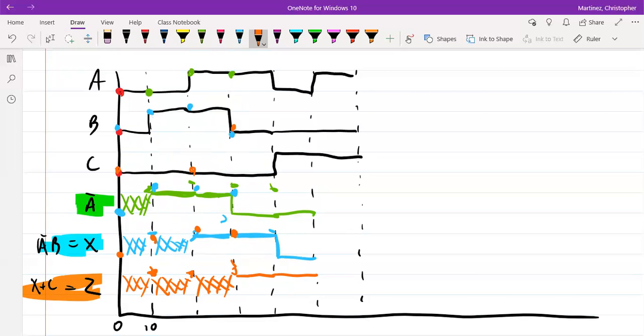All right, so that takes care of our simulation piece. You saw how to make a simulator using that Circuitverse web program. We talked about function diagrams, which just pinpoint what the output should be on a waveform showing how items will change over time. And then this last piece is our timing diagram, which looks at the actual delay of our gates as we move through the circuit. Right, so that takes care of all the simulations of module 7.